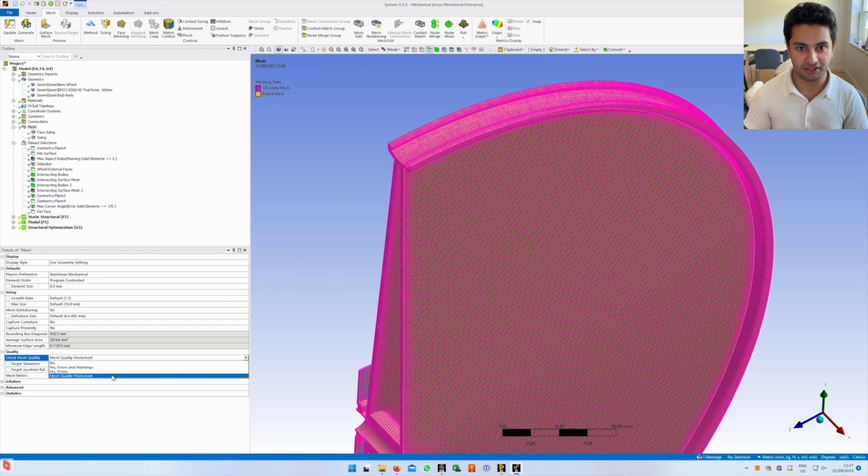So in second year, third year as well, I think we're taught for both Ansys and Abaqus to do a mesh convergence study. What you do there is you start out with a very granular mesh with large elements, and then we increase the number of elements, decreasing the element size over and over.